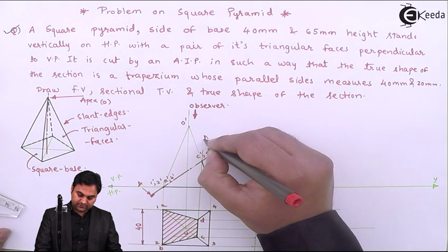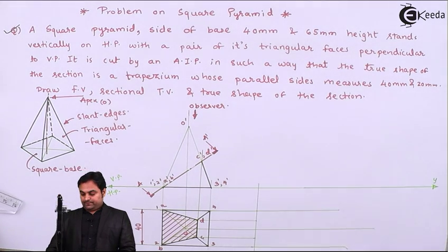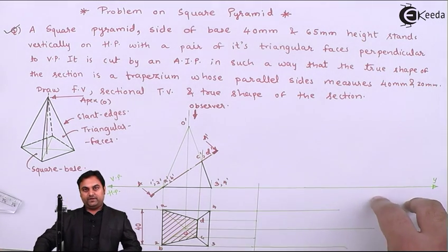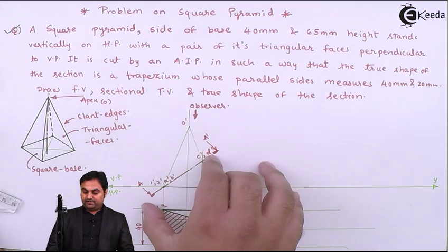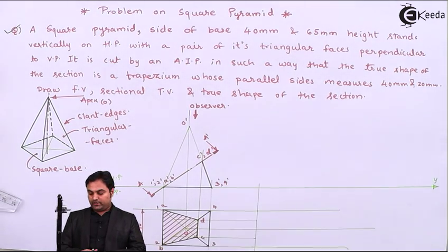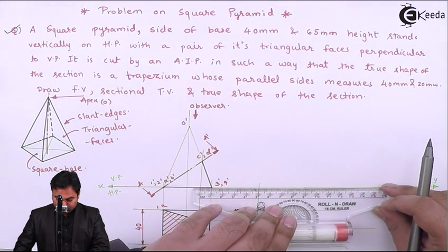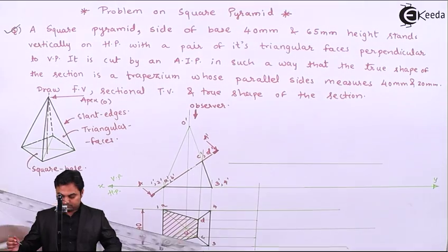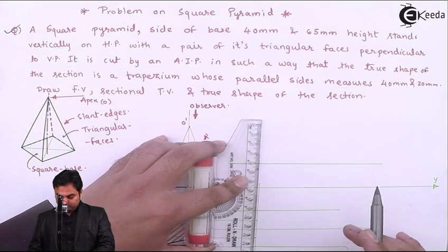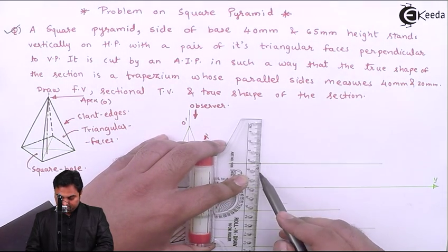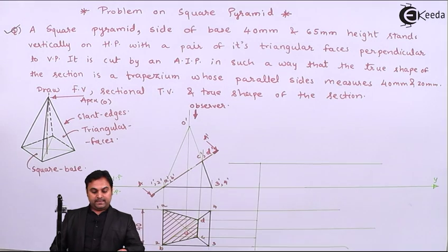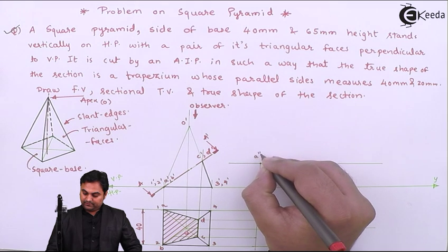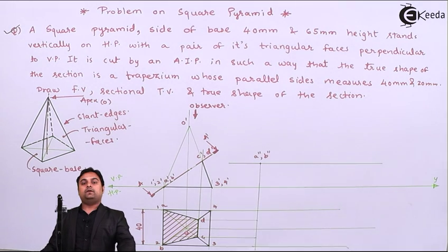Cutting plane A dash. Next, I have to draw the true shape of the section, and for that I will have to draw the true shape in the HP because the section is here, and make this cutting plane parallel to XY in VP. So drawing a light horizontal line here. Now this vertical line which I have taken previously as 40 mm will be projected up, and that will be point A dash B dash, or here I'll say A double dash B double dash for us.